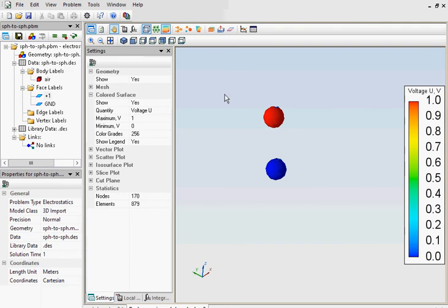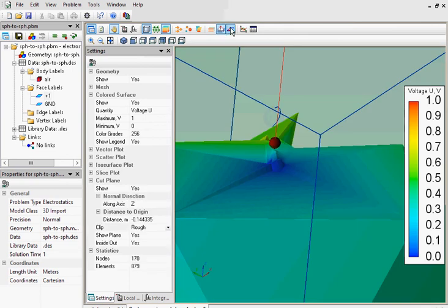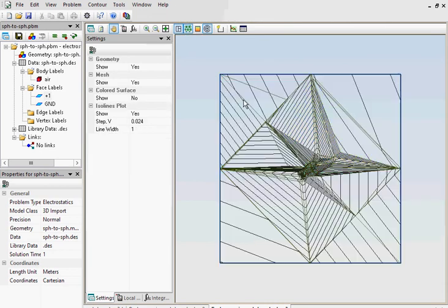Let me show you. I will unhide all. I will use the cut by plane tool and switch to the 2-dimensional section window. And here you can see the field lines. In fact, these lines should be smooth curves, but we have line segments with sharp corners instead. That's because the finite elements are huge, and inside each element the potential distribution is considered to be linear. If we had smaller elements, we could get a better approximation to the smooth curves.